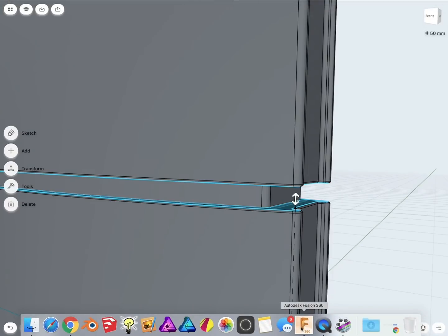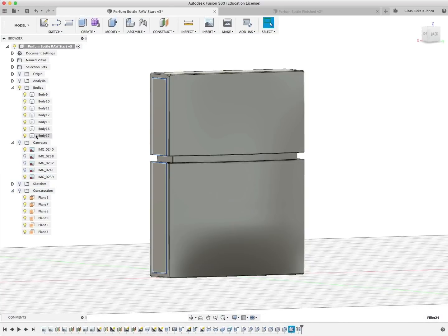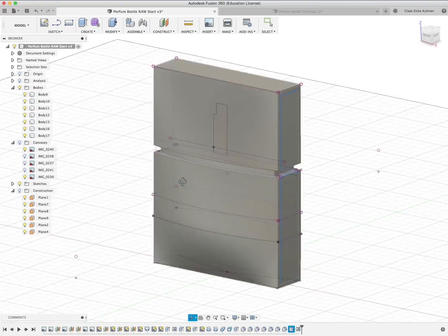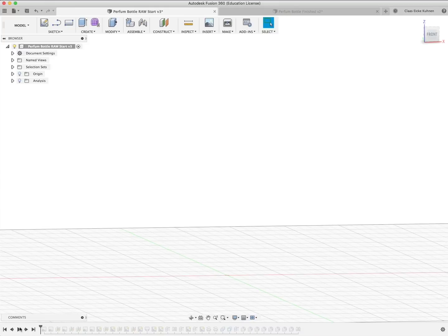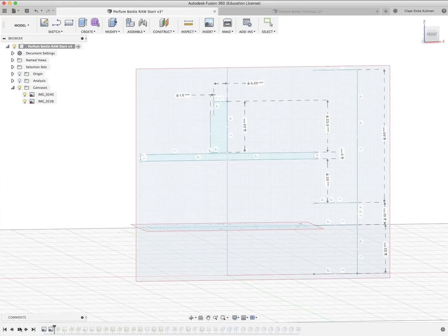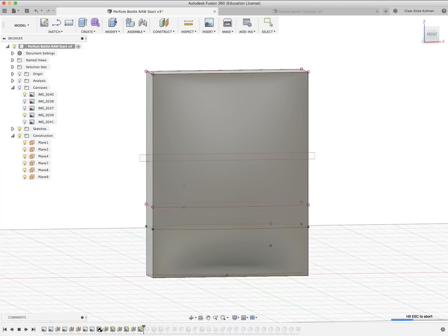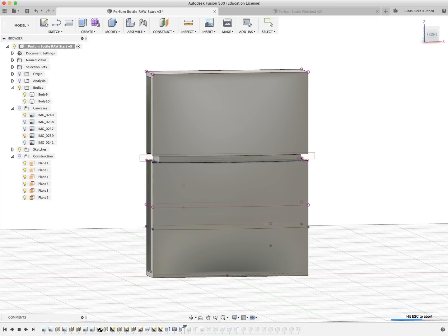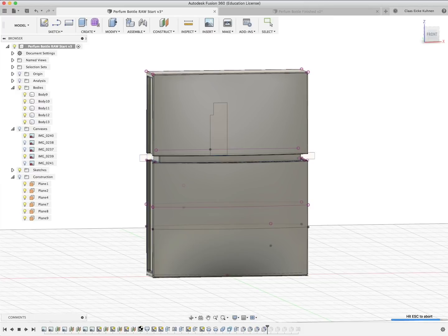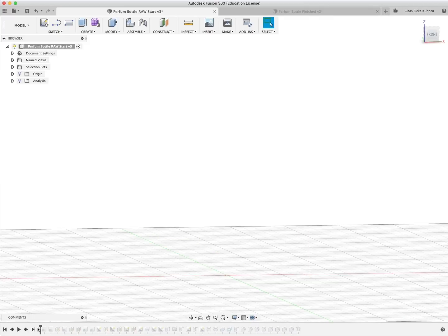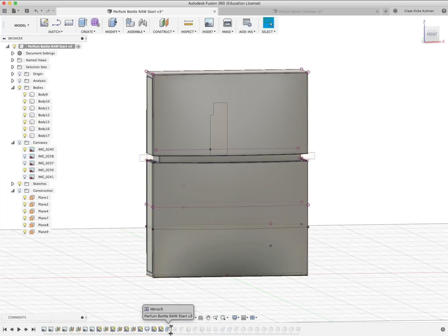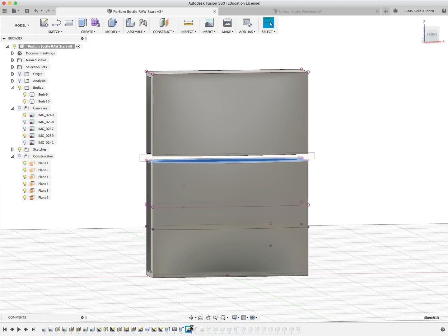Let's go to Fusion. And the downside with parametric modeling is essentially this is kind of like a timeline. So I'm just going to hit play, and it shows you all the individual elements step by step. It puts it all together. And you cannot remove a previous point or element, let's say like a sketch, and then expect the software will understand how to build the rest, because essentially this is like next step, next step, next step, next step. So this result will be fed to this result. This result will be fed to this tool. Then the result there will be fed to this tool.